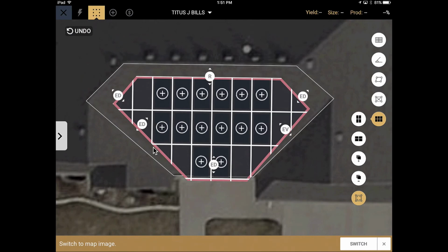So if you see that this green shape extends out beyond, you are seeing the actual roof space available, rather than just taking a top-down image of a home and trying to guess at the actual surface area. So anything inside of this pink is really the actual roof surface area, and you're able to put panels in there. Now I'm going to turn off the setbacks.